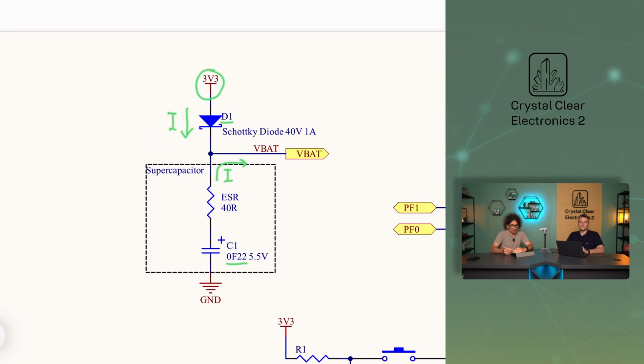In the wiring diagram, the capacitor is indicated by the framed part. The capacitance of the capacitor is very high, so that when voltage is turned on, it would cause a very high current to flow, which should be tried to be prevented. This could be avoided by using a current limiting series resistor, but as the capacitor we have chosen has a relatively high internal resistance, this is not necessary. This is pointed out in the wiring diagram.